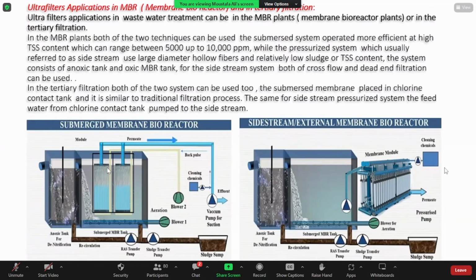And the other compartment is the MBR reactor. Okay, this is the main stage during which we have the treated water. We have here an enormous amount of sludge carrying, of course, microorganisms, which can be bacteria, flagellates, or other kinds of microorganisms. A very wide variety of microorganisms can exist.